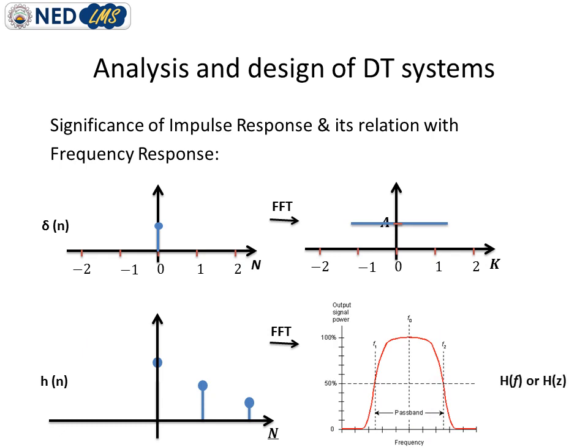So we can say the impulse response in the time domain, which is represented by h of n, and by taking its fast Fourier transform, which is FFT, we will obtain h of f, which is the frequency response. So this is the shortest and the most efficient method to determine the frequency response of any system, and this is how the impulse response is related with the frequency response. Impulse response is in the time domain, and if we take the fast Fourier transform of that impulse response, we will obtain the frequency response.